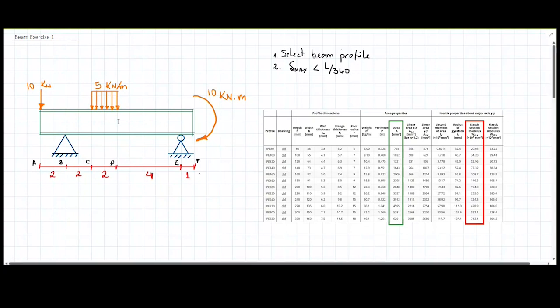It could be a compressor rotating at 60,000, 90,000 RPM, which means that any deformation in a shaft rotating at such high speed would generate a tremendous vibration that would end up destroying the whole equipment itself. So the requirements for shaft deformations are higher, meaning very tight. They are not giving you any gap or slack when you are trying to estimate or design a shaft. For structural beams, they are a little bit looser, let's put it that way. But still, they are kept within very nice tolerances.